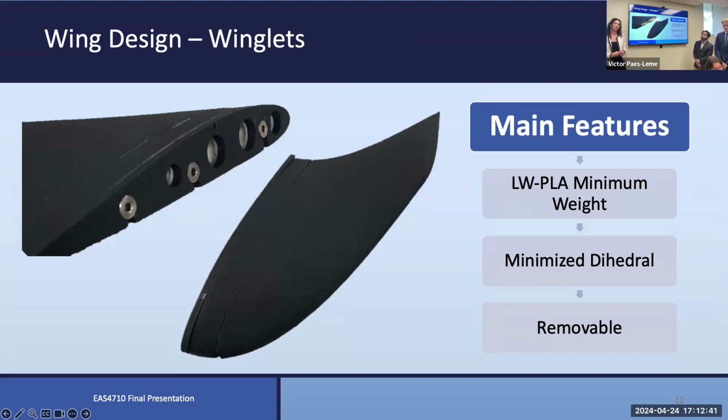I think when you guys explain this one, you said minimize dihedral for decrease the bending moment. Yeah, so in the textbook, it pointed out that one of the issues with having winglets that were pointing up was that then you would have some lift component that was actually pushing the wing into the fuselage. So it did provide not a hugely significant, but some contribution to the moment going inwards. That is what we're referring to, the dihedral of the winglet itself.